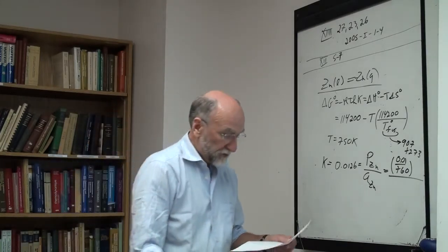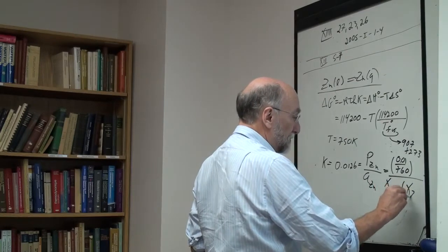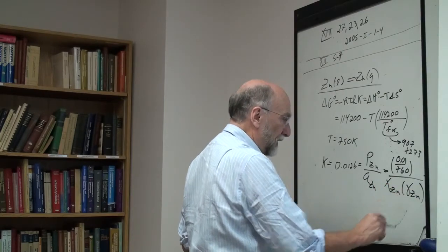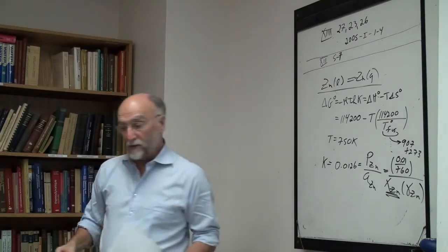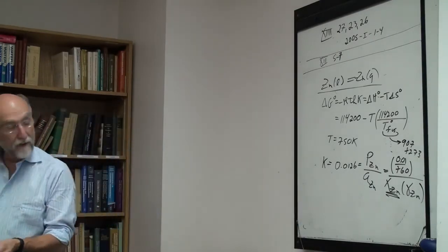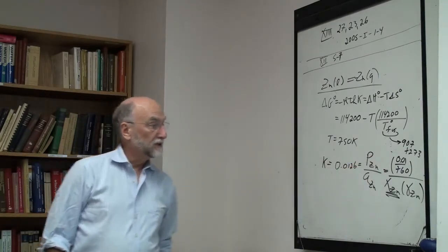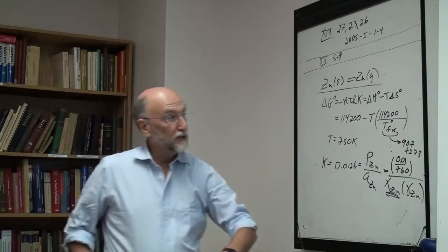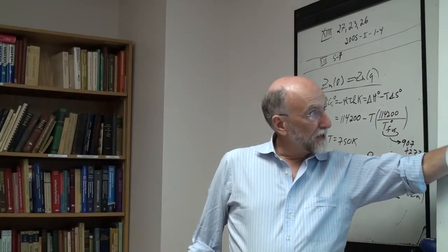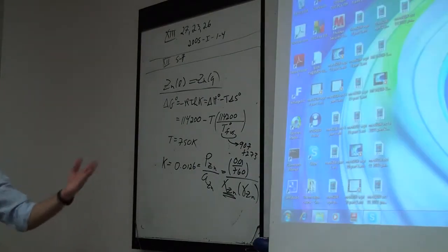And the activity of zinc is the mole fraction of zinc at equilibrium times gamma zinc in the liquid. So this is what you're trying to calculate, when this is at equilibrium with the gas phase with this partial pressure of zinc. What is the mole fraction of zinc? That'll be the minimum mole fraction you can get to. You're trying to take this liquid and distill it until you end up with the minimum mole fraction of zinc.